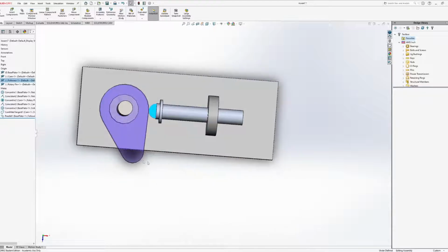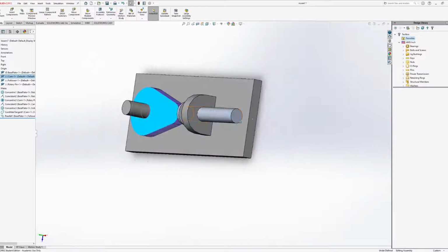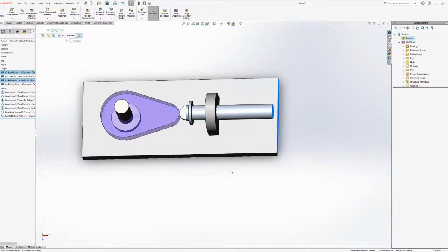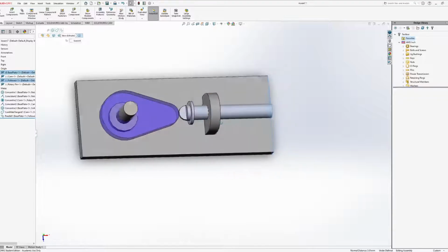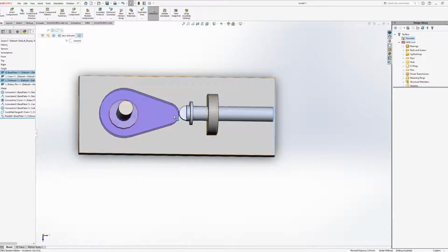So I'm going to make an assumption as to where the minimum distance between these two faces should be. If I click on these two surfaces, it's telling me that it has a normal distance of 3.01. So it's about 3. If I were to give it a minimum distance, I might give it a little bit more leeway in the event that weird things happen. But we'll kind of play that by ear.